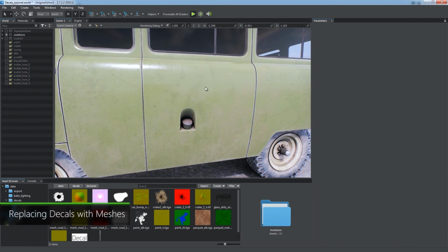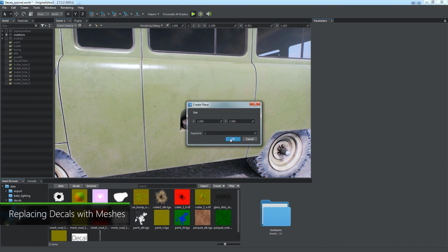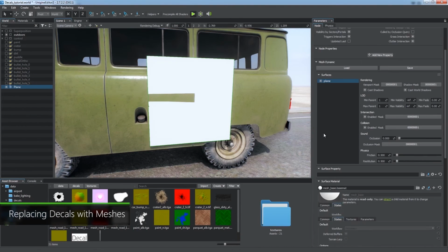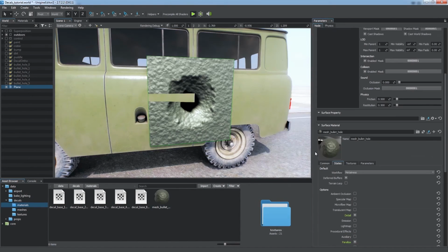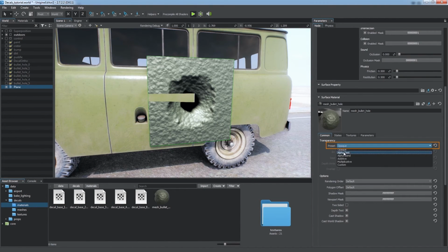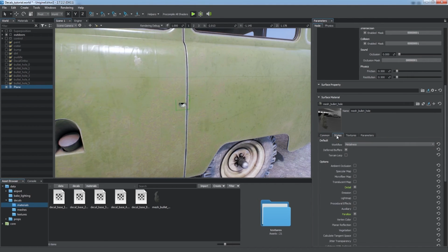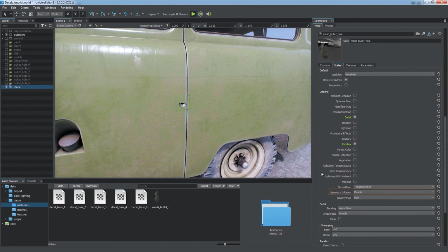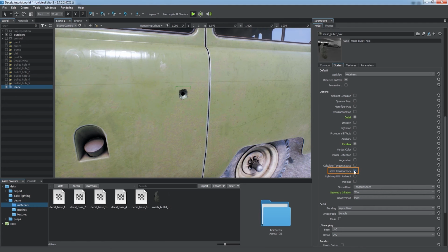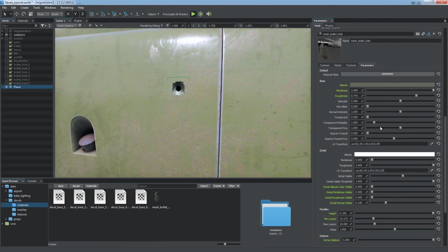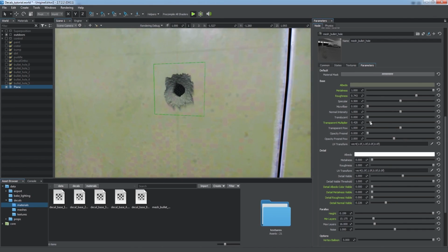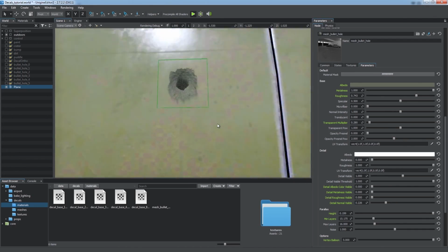If you have a geometry that is flat enough, you can use a plane primitive instead of a decal to save some performance. For alpha masked objects, the alpha test blending preset should be selected. Pump the geometry up a bit by setting the geometry inflation option to wire to avoid z-fighting of surfaces. You can also fake semi-transparency by enabling the jitter transparency option. Although this approach produces noticeable noise at closer distances, it really is useful in terms of performance optimization.